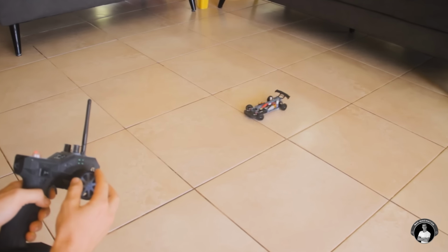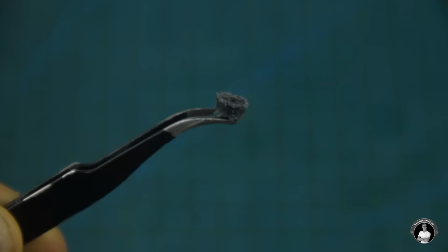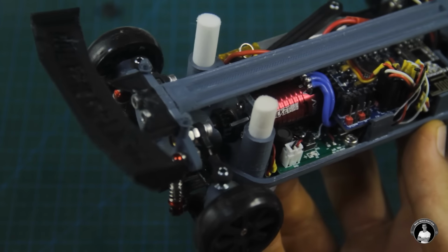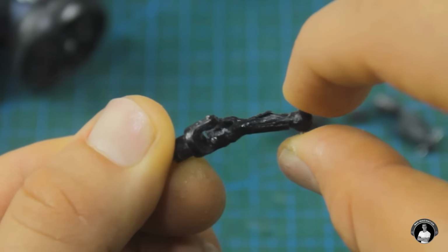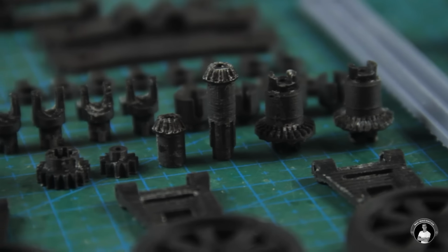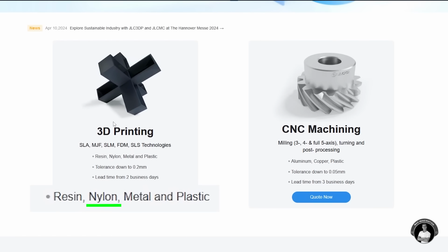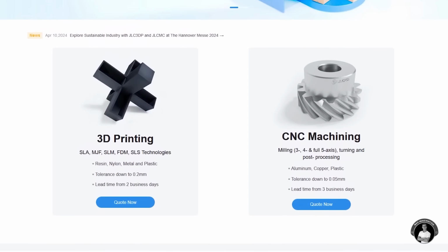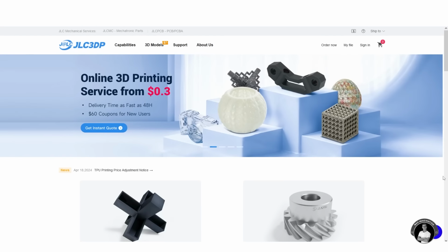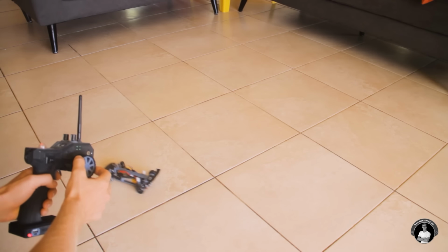One thing to keep in mind is that if 3D printed PLA gears are used, they'll eventually wear down like this pinion gear did from the motor's heat, and other rotating parts such as the joint axle damaged from high speeds. So I highly suggest having the parts under tension to get either 3D printed from nylon, a tougher plastic, or metal machined from aluminum by JLC with their parts manufacturing service. With stronger materials used, you'll have a long-lasting, thrilling RC car to drift around with.